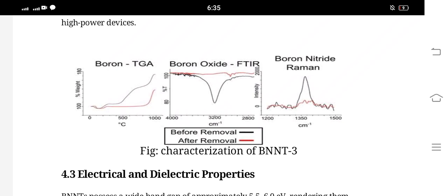The presence of multi-walled concentric layers indicates that the boron nitride nanotubes consist of few-walled or multi-walled boron nitride nanotubes. The smooth tube walls and consistent interlayer spacing demonstrate high crystallinity and low defect density.